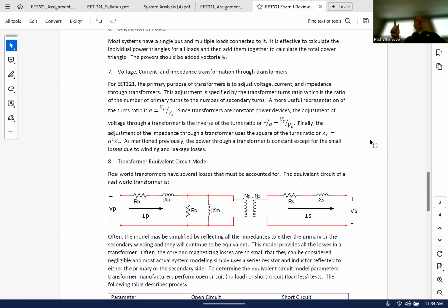All I see is voltage and current, which looks like an effective or a Thevenin equivalent impedance for representing the transformer and whatever load you have. So you just reflect that impedance onto the primary or into the secondary, just depends on which way you want to go, and that's using the turns ratio squared. Okay.